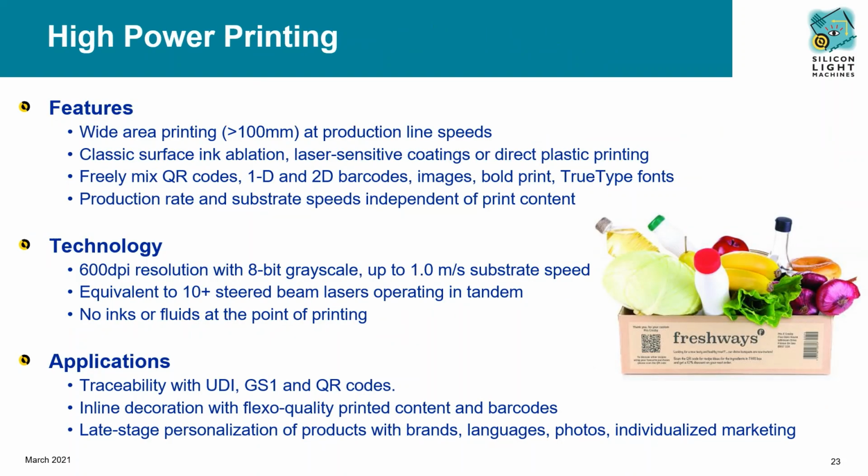Similar to material processing and laser marking, we believe the LPLV brings numerous unique advantages to high-power printing. The high-power modulator works with pulsed or continuous lasers, with modules available for wavelengths from UV to NIR, enabling any print technology with the LPLV platform. Unlike with beam scanning, an LPLV-based 1D scan system can have throughput speeds that are entirely agnostic to the print pattern. Your complex QR code or detailed logo can be created with the same ease as a simple letter.